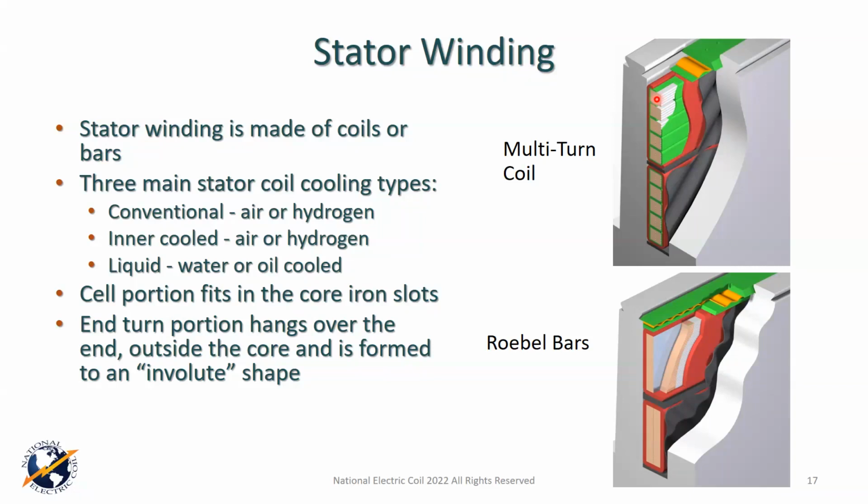During the coil manufacturing, during the winding of the machine, and then during operation. Because of that, it's not just the voltage stress you see on paper. It's also got to be robust enough to deal with the mechanical aspects. That's why we traditionally do everything we can to put turn tape into a design to help prevent that failure. I'd recommend, if you're writing or looking at specs, that's a good thing to have in your spec: dedicated turn tape, if at all possible. And usually it is, but you've got to push them.